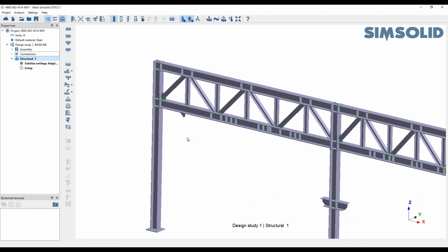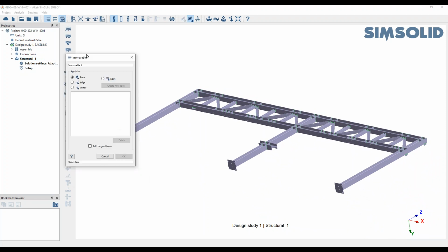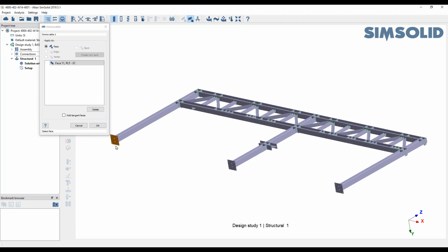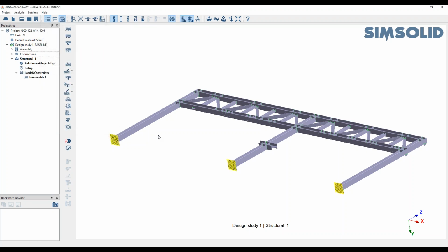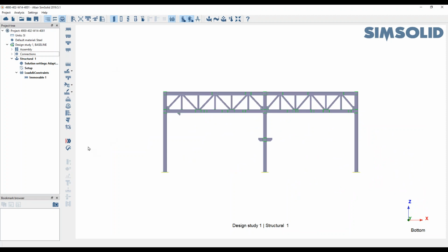So let's just first of all do the easy task of grounding the columns. So pick that one. So these are fixed to the ground, and we're simply going to apply a simplistic load. It's a gravity load, and we'll get a stress due to its own weight of the frame. And the gravity is defined by a vector automatically, so that's going to be in the -z direction. Okay, and I think we can check if everything's okay.